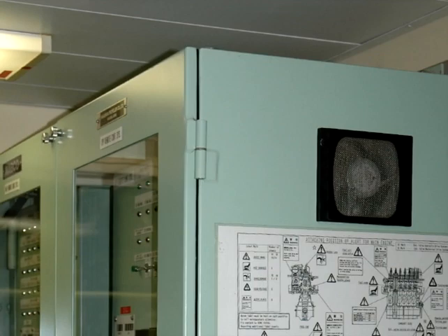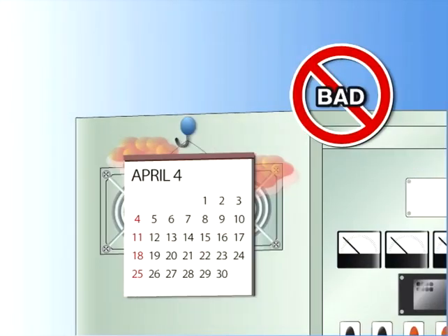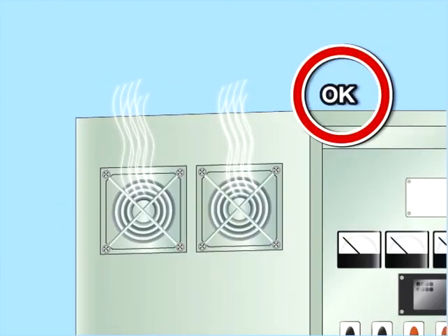For effective cooling of electrolytic capacitors, care should be taken so that the suction and exhaust fans of the inverter or UPS are not choked with dust or other debris. Fans should be inspected regularly to remove dust and ensure they are functioning properly.